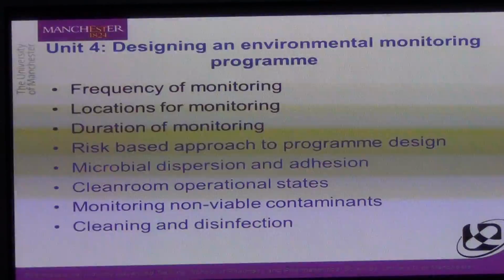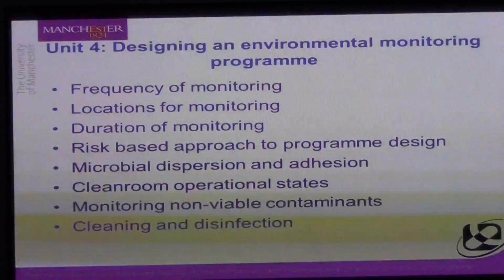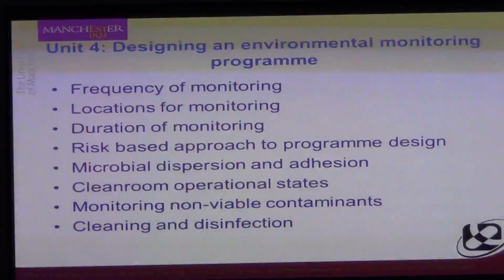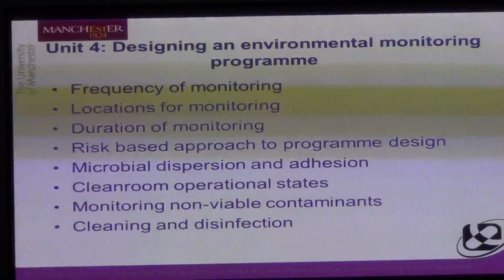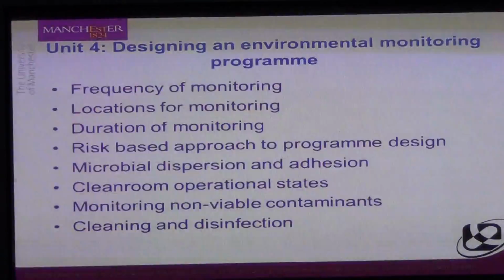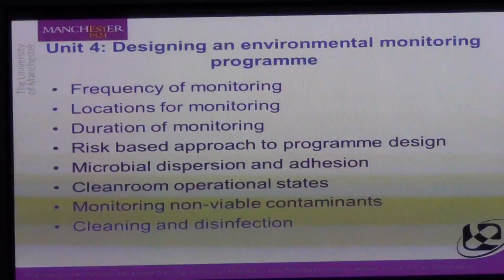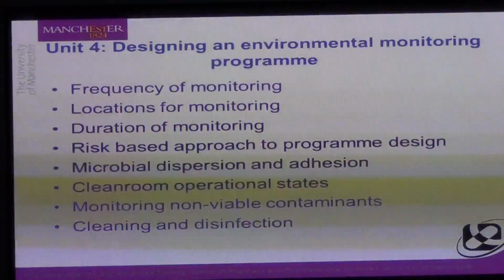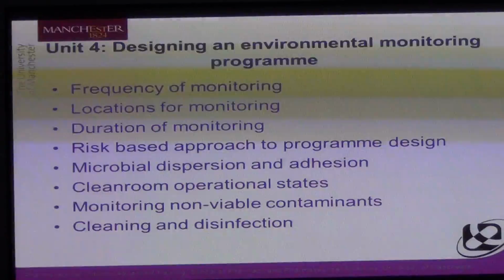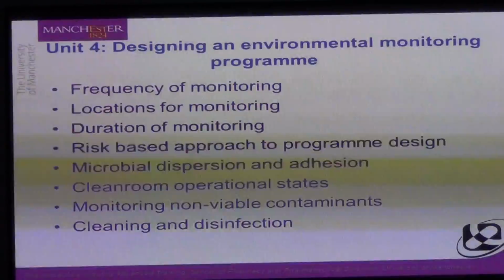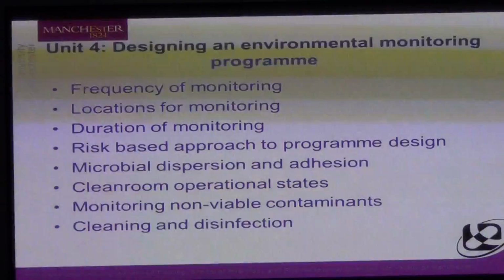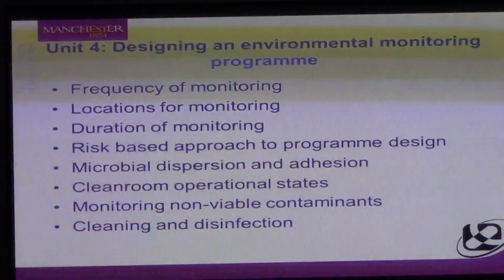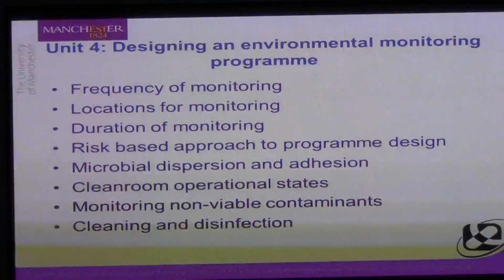It then considers how microorganisms are dispersed within clean rooms and how they adhere to surfaces and how that affects the recoveries that we get from our environmental monitoring techniques. It then looks at clean room operational state. So for instance, should the monitoring be done at rest or the in-use condition? It also looks at particle monitoring or the monitoring of non-viable contaminants and how cleaning and disinfection can inform these aspects of environmental monitoring design.